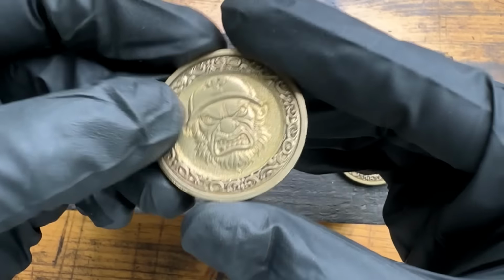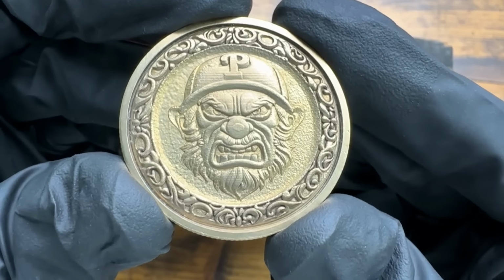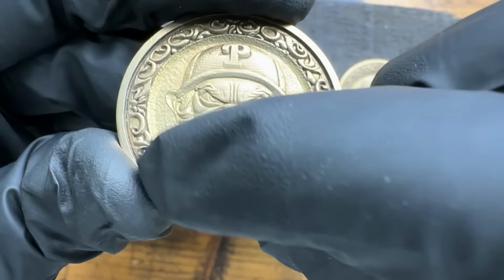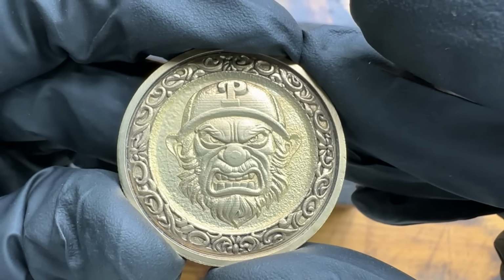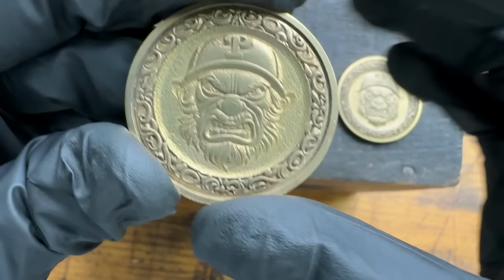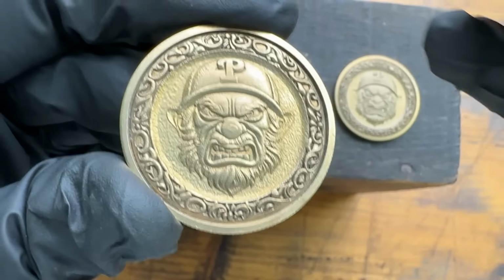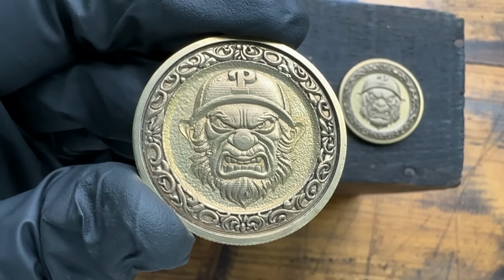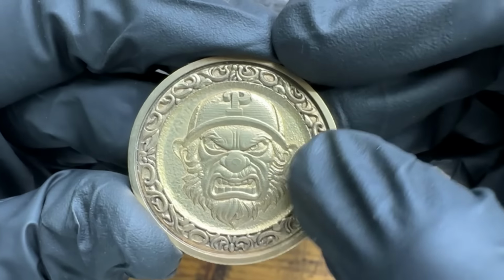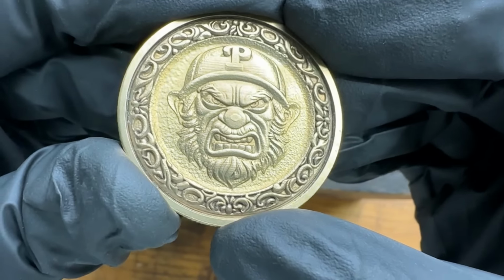So starting with the lower frequency. If we look at our image here, the thing that stands out the most is just how rough and noisy the background is. Look at that. It looks like I textured it on purpose, but I didn't. That's just what happens when you run a lower frequency with a more powerful pulse, with more gap time in between the pulses. It's just going to impact and crater your image much more and leaves it with an overall noisier look.